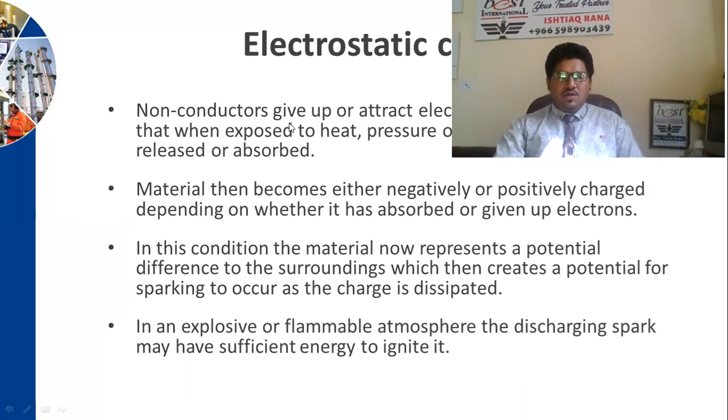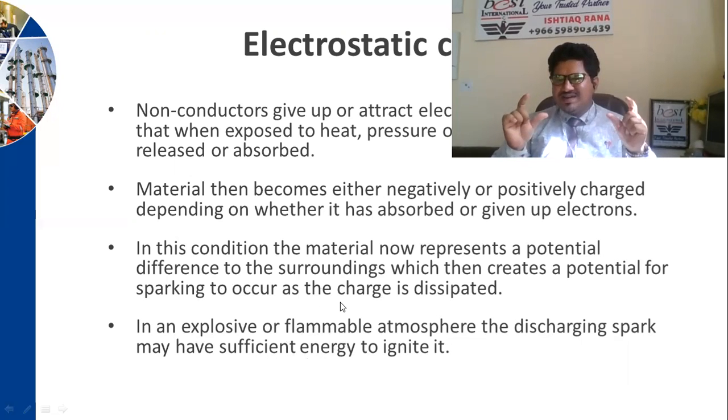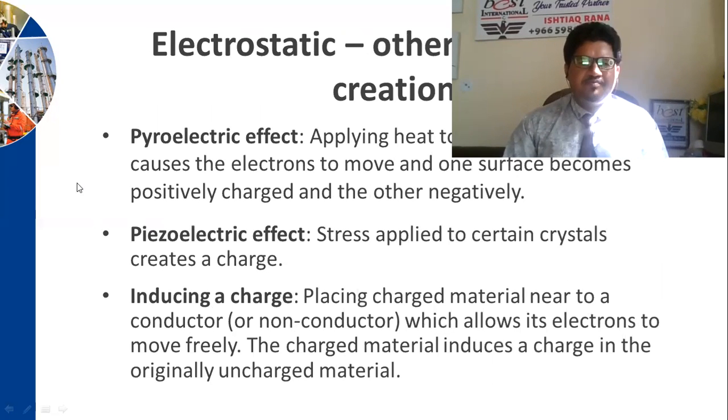With electrostatic charges, conductors give up or attract electrons relatively easily when exposed to heat, pressure or friction. The material then becomes either negatively or positively charged, depending on whether it absorbed or gave up electrons. In this condition, the material represents a potential difference to the surroundings. We then create a potential for sparks to occur as the charge is dissipated. In an explosive atmosphere, it may have sufficient energy to ignite it.